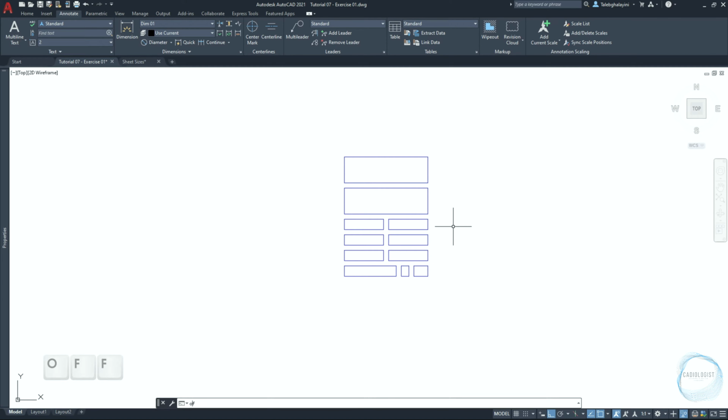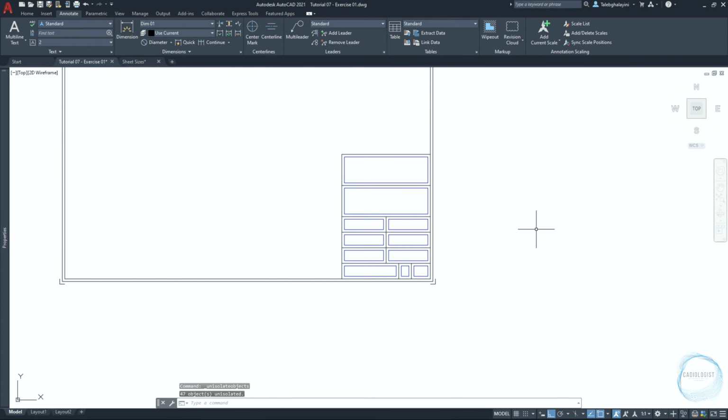As I told you guys, I will go to the Offset command again in order to change the erase setting to default by choosing No. Click on this tab from the status bar and choose End Object Isolation. These blue rectangles were made just to accurately create the title block text. Besides, I wanted you guys to practice the offset and boundary creation commands.